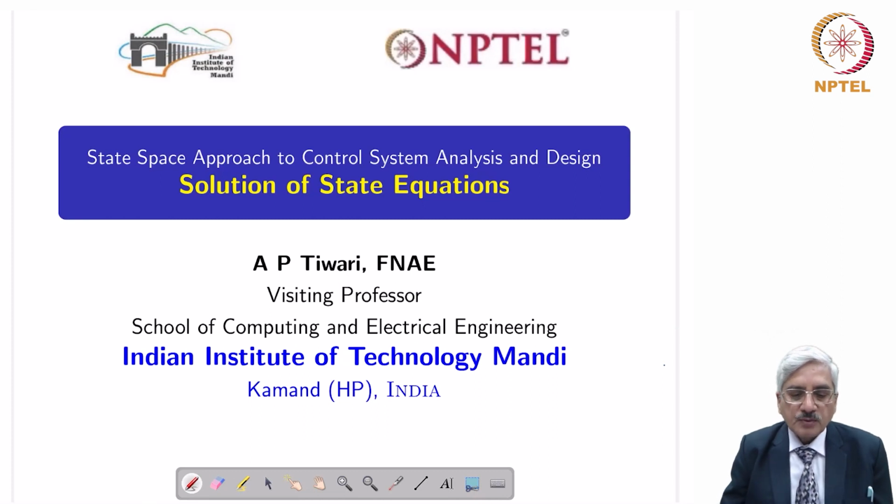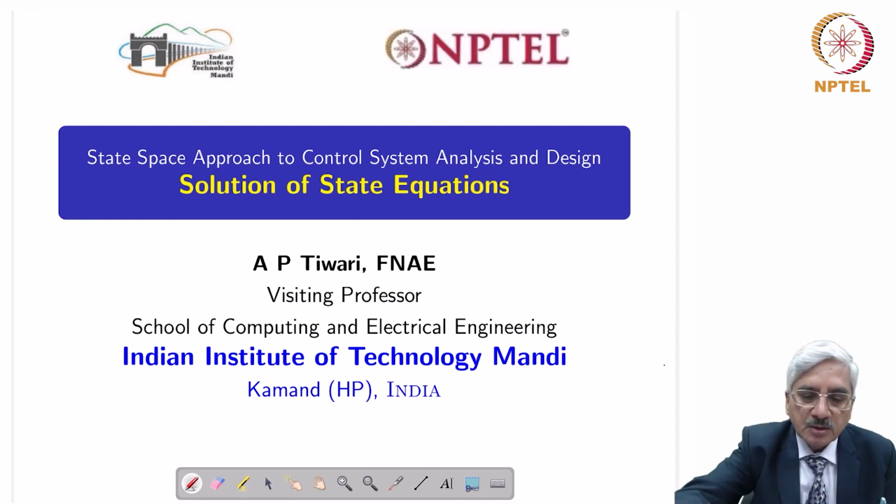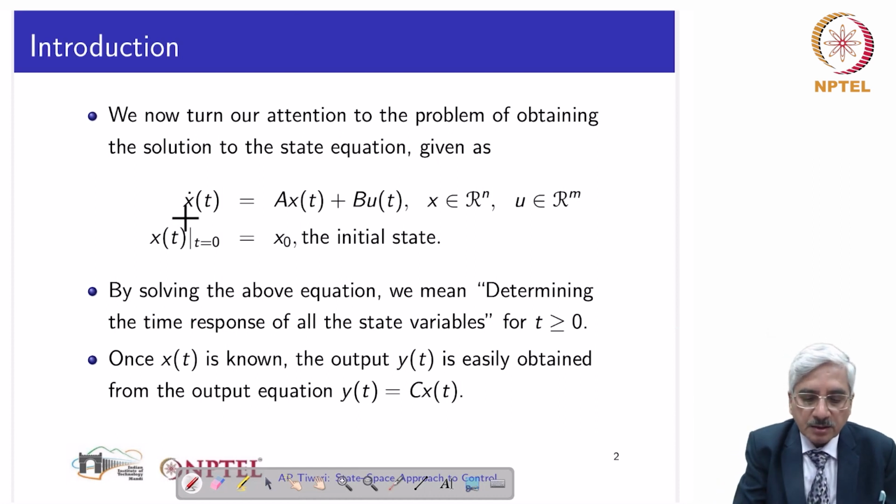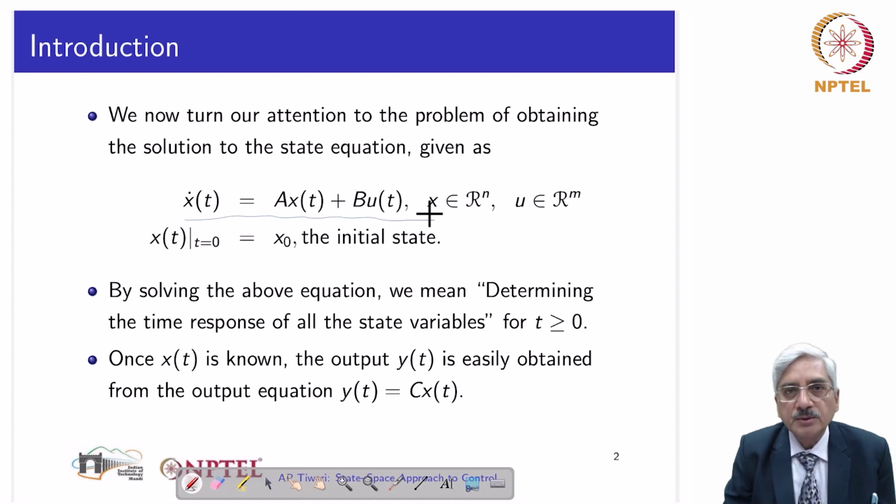Now, as we move to the solution of state equations, the basic motivation behind this is to understand the system behavior. So, we are given the state equation in the standard form x dot equal to Ax plus Bu, in which x is an n-dimensional vector and the input u is an m-dimensional vector.